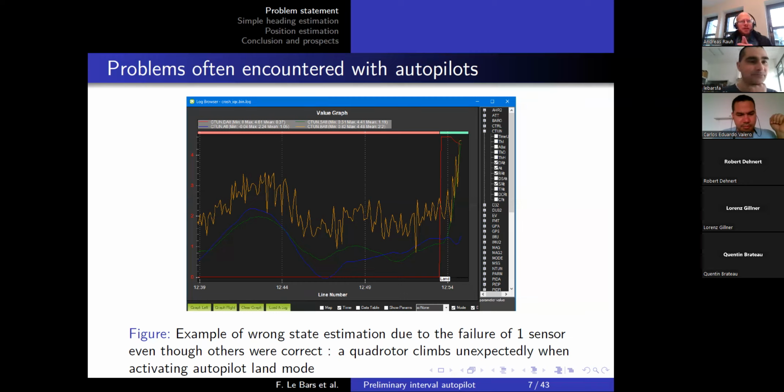I think in cases where you have some sensors for which you have to integrate the signals temporally, it's quite easy. Then you have an uncertain time span of integration, and you could include the corresponding values in the corresponding interval as the outcome. But if you're directly using the sensor information without any additional signal processing afterwards, and you just have a measurement at some point in time where you don't know exactly when, I think that's more tricky.